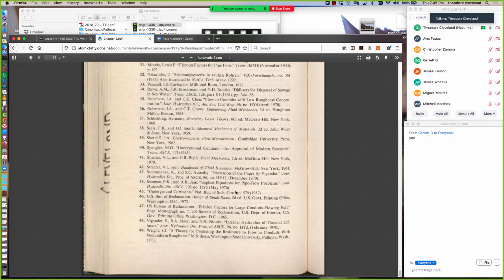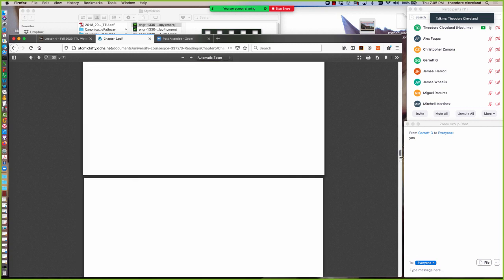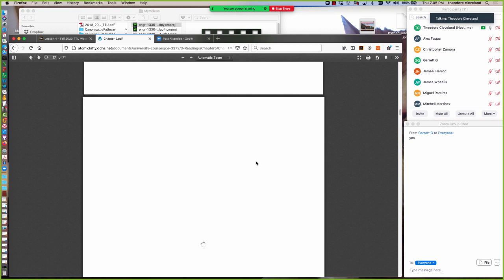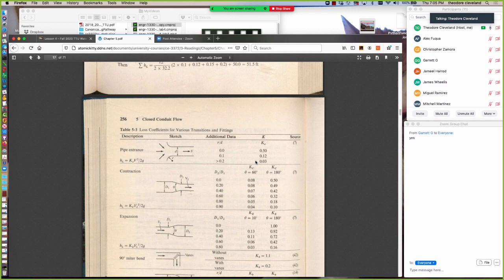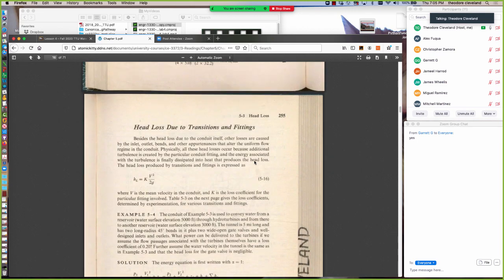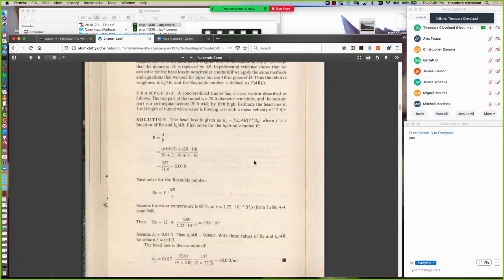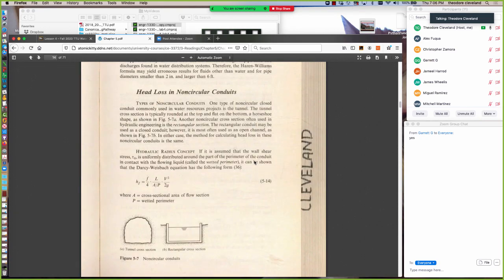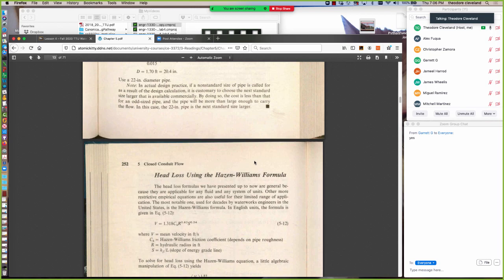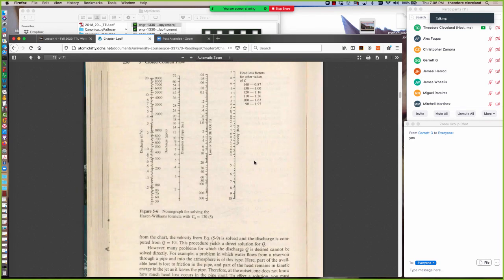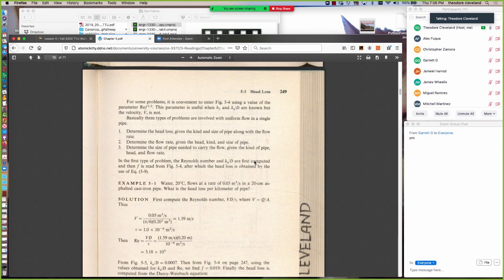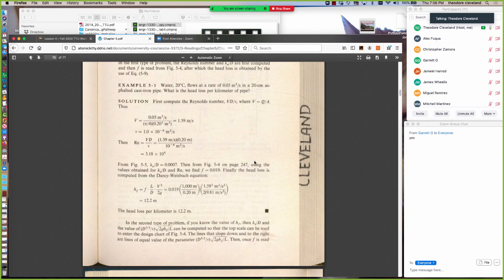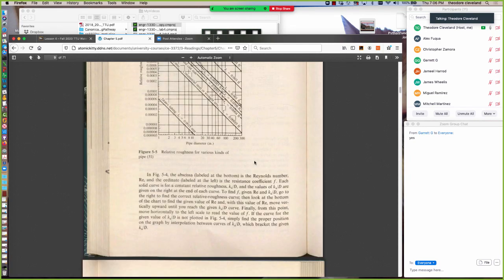So right here, explicit equations for pipe flow problems, and there's 2 categories of them. One is to predict discharge given head loss. The other is to predict diameter given head loss and discharge. And they both can be used in iterative fashion to infer unknowns that aren't in the explicit portion. So for instance, if we know diameter and we know discharge, we can compute the required head loss to make it so. And let me find the equations again.